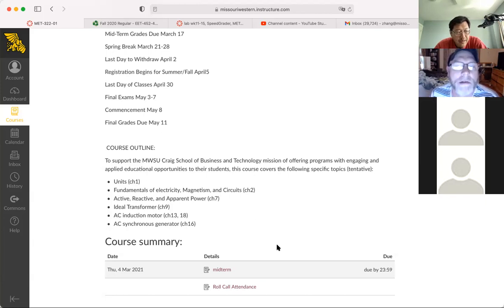Wired for low voltage will be the delta. Wired high voltage will be the Y. Let's see. 1, 2, and 3 go to 9, 8, and 7, and 4, 5, and 6 all go together. That I remember.